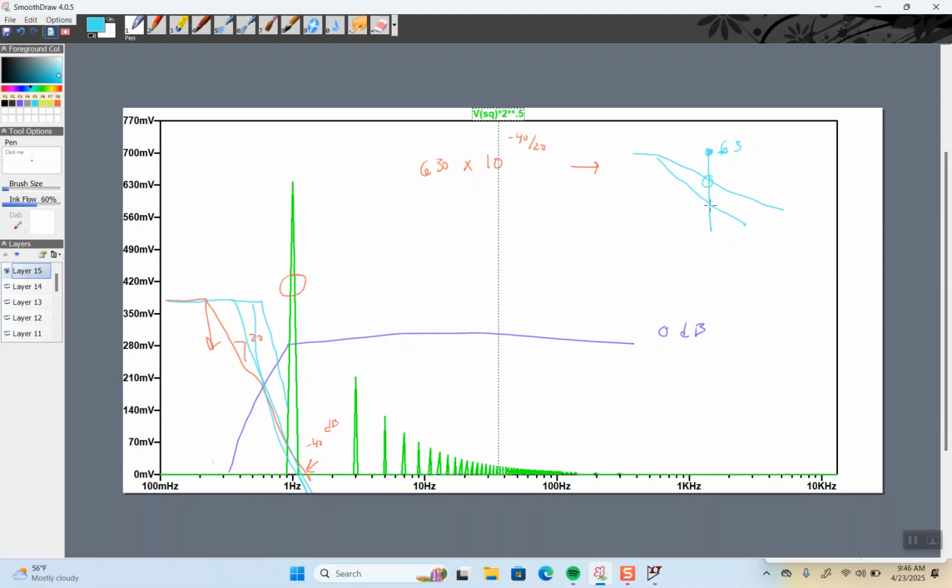Let's say I want to keep just that frequency. I would put a band around it. Again, it's just a sketch, right? So now everything else should be attenuated, right? And let's say it's coming in at 210 millivolts, but I want it up to 1. Well, then I would have a bandpass with some gain. It would make it bigger.